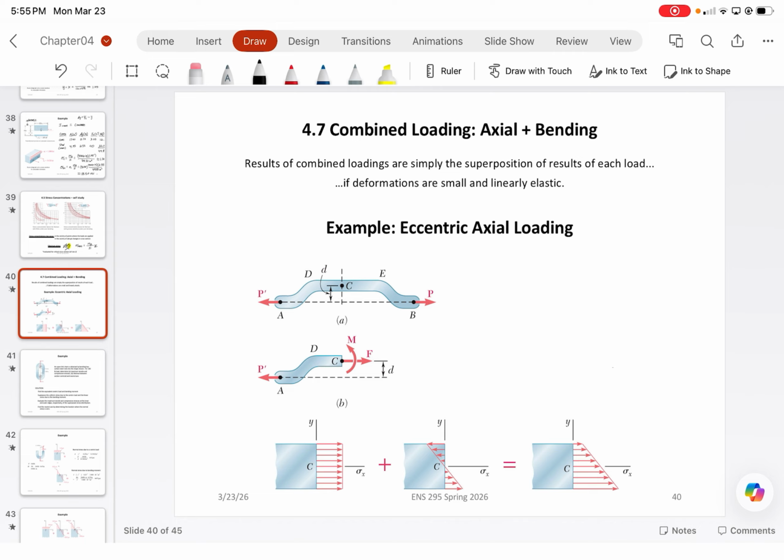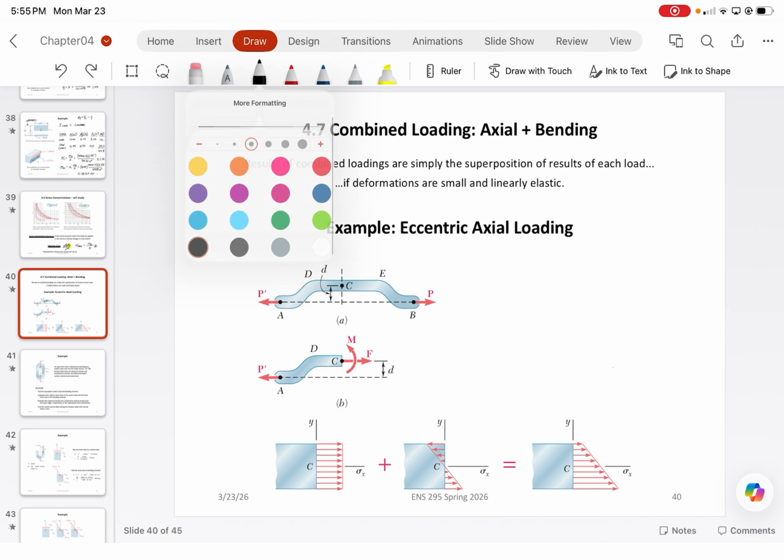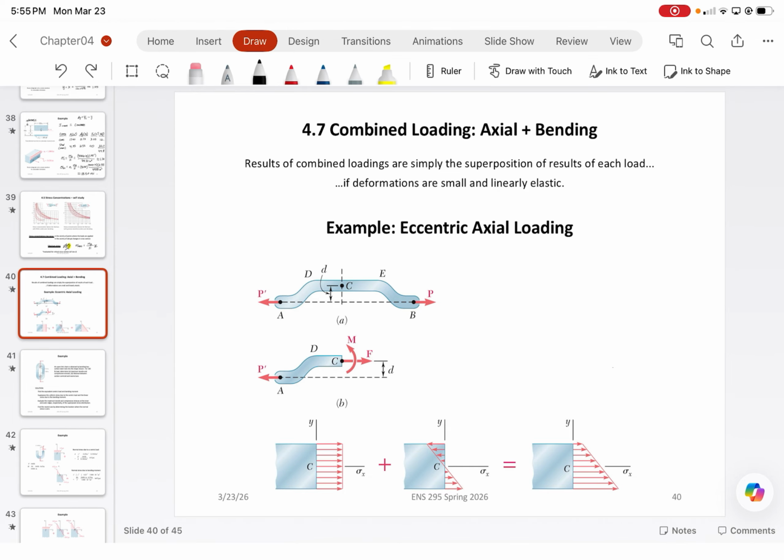And then because of the moment arm, which is defined by this term D, we actually have normal stresses developed by bending. So what we end up with is this term here, which is just going to be our standard internal force divided by the cross-sectional area, and then our equation from bending, which is just going to equal our My over I term.